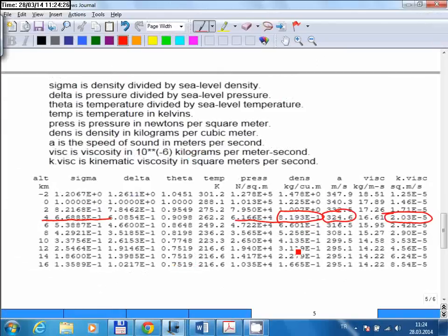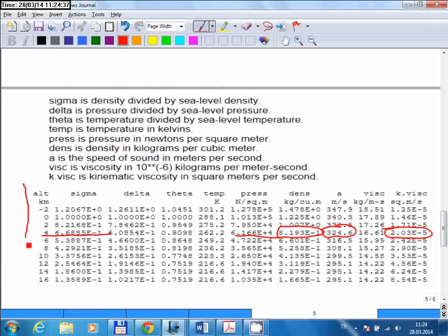Okay, so in your future exams and homework problems, or whenever you need to make some aerodynamic calculations, you should use these tables, the standard atmosphere tables, and in the exams I will be giving you these numbers. So you can just take the number from these tables, and you can do just linear interpolation. For example, the table gives the values at 4 kilometers and 6 kilometers, but if you need to know the density at 5 kilometers, you can calculate the corresponding number using linear interpolation. Okay.